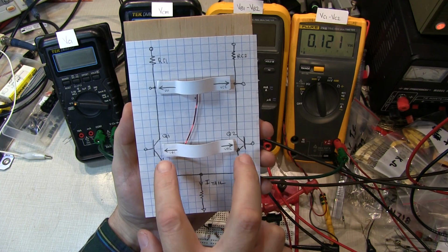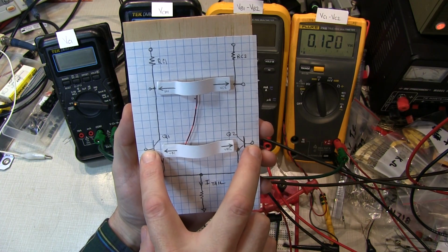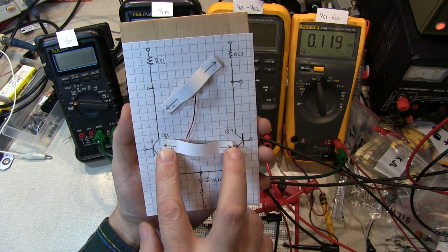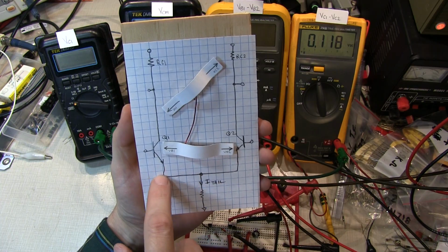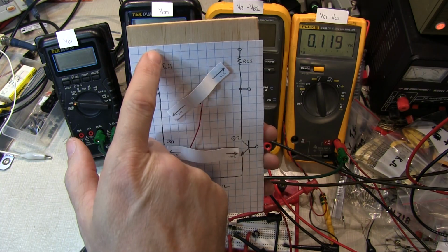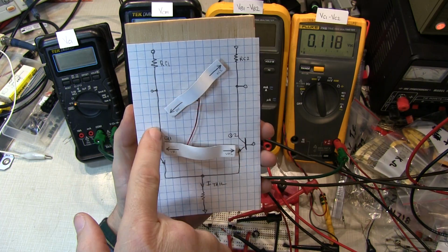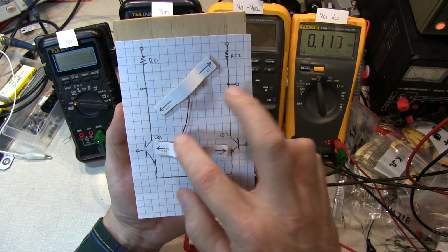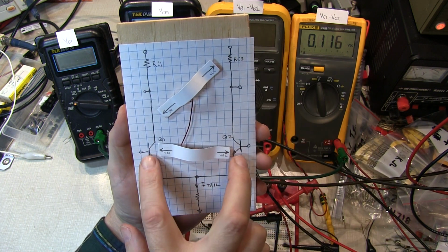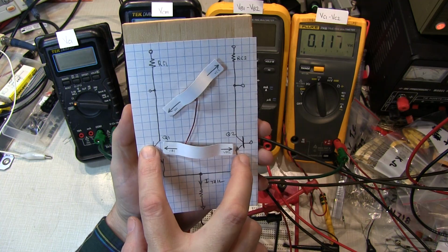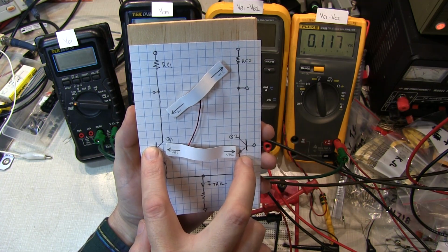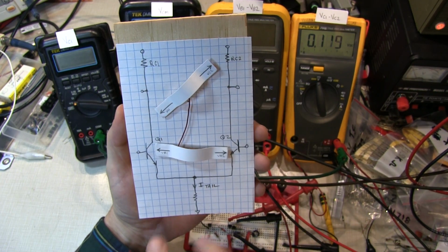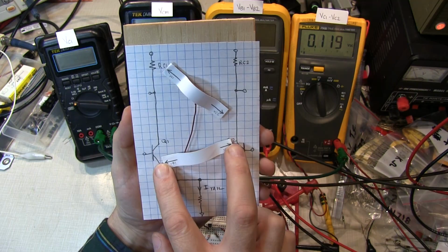So if VB1 is equal to VB2, they're both at the same voltage level, and the collector voltages are at the same level. But if VB1 goes up, then more of the current goes into Q1, dropping more voltage across R1, and this voltage drops. Less current is going into Q2, so we have less of an IR drop across R2 and its voltage goes up. And you can see that the circuit has gain. A small change in VB1 versus VB2 can mean a large change in the difference between Vout1 and Vout2. And the same holds true going in the other direction.